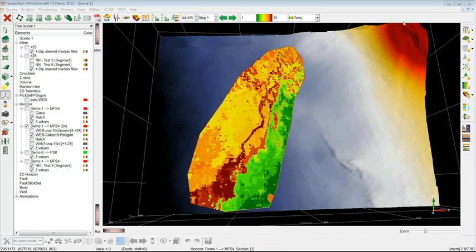Yeah, data quality is of course an important item. If you go into the F3, if you do it on the raw data, you will see that your segmentation will also pick up an acquisition footprint. So you get striping in the inline direction, in this case through the area.